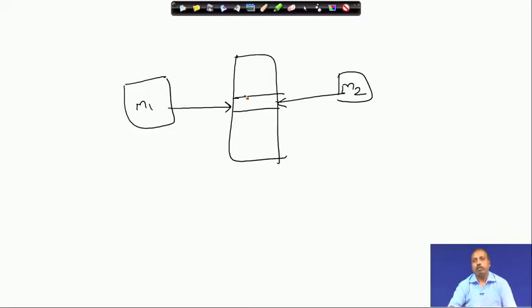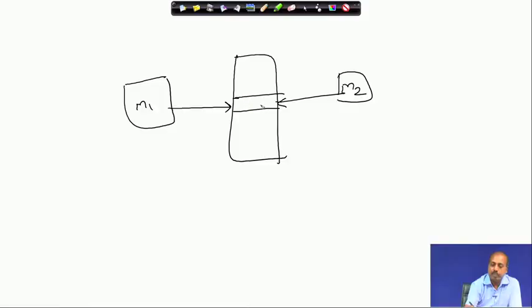This is a very important problem when we consider operating system design. So, what is done is that the updation, the writing onto this location, is prefixed by a lock. As a result, if M1 is executing this, then M2, while requesting the memory, will first see the lock line of M1, and if this lock line is low, it will not be allowed to access the buses.